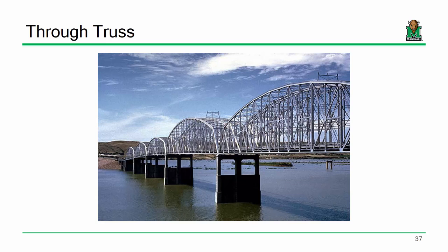And the way I can tell you that is look at these trusses. Isn't it funny how these trusses kind of look like moment diagrams stacked over and over again? That's because they are. I mean, again, a truss is really just a beam with holes in it. And what they're doing is they're trying to arrange that truss to support those loads. And those loads are moments. So, you know, you look at this and you say it's really acting more like a beam than you would think.